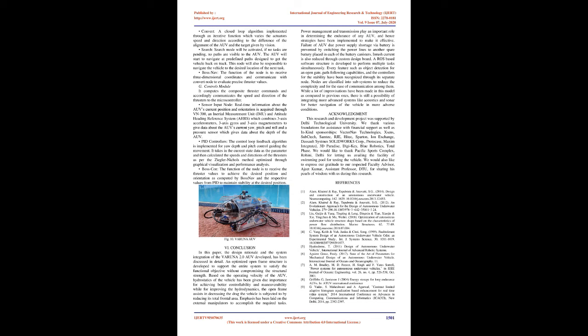The I term uses the past value of the error and multiplies it with a weighting factor Ki. It sums up the error term over time. This results in an increase of the integral term even with a small error term. The integral response will continually increase over time unless the error is zero, so the effect is to drive the steady-state error to zero. The D term predicts the value of the error and multiplies it with a weighting factor Kd. The derivative controller component causes the output to decrease if the process variable is increasing rapidly. It is proportional to the rate of change of the error term. The effect of each of the controllers Kp, Ki, and Kd are summarized below.